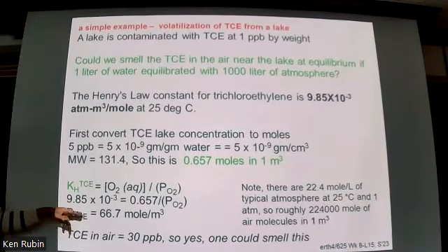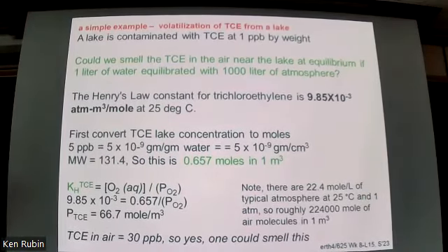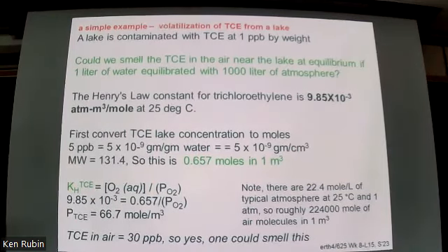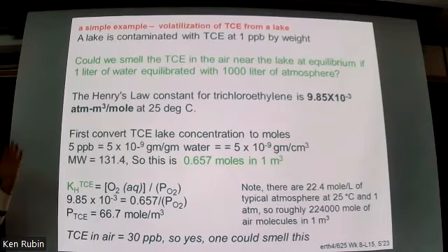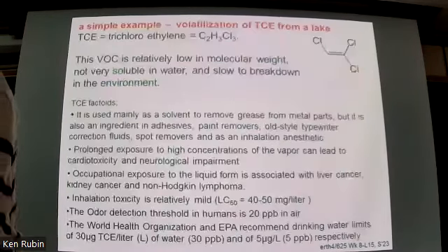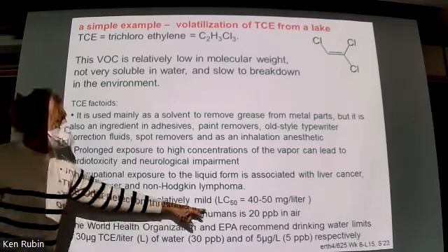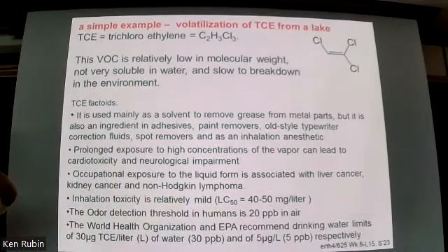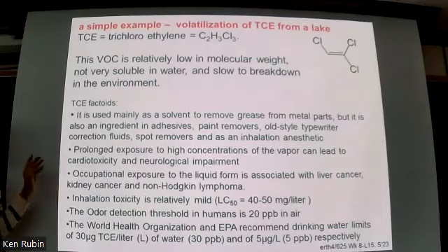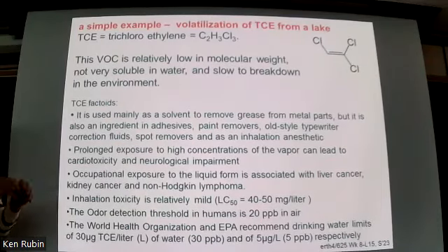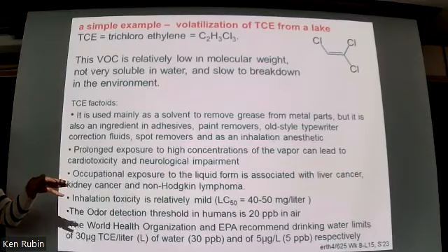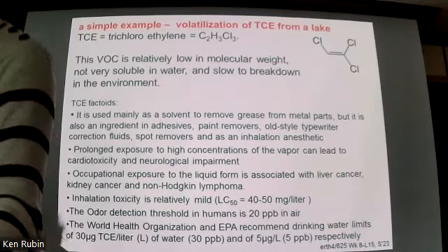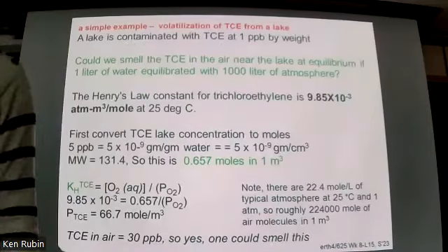Right, the trichloroethylene is a small component of the total number of molecules or moles of gas in the atmosphere. And the odor detection limit, which is back here on this slide, is given in parts per billion, right? Meaning fractions of the total by weight. So we basically have to calculate the amount of trichloroethylene relative to all the other gas molecules, convert them with their respective molecular weights into moles, and then figure out the amount.